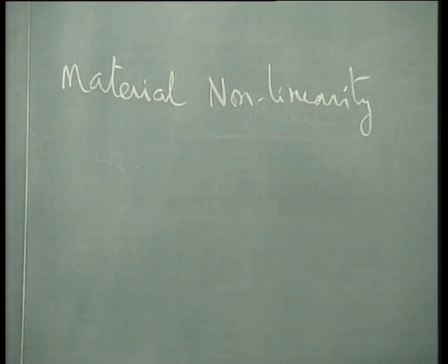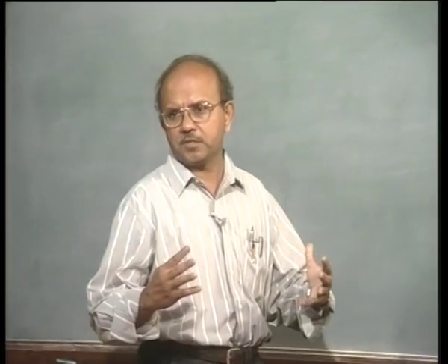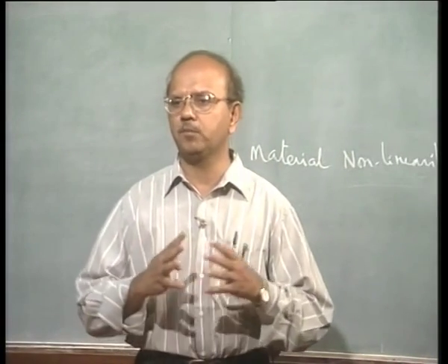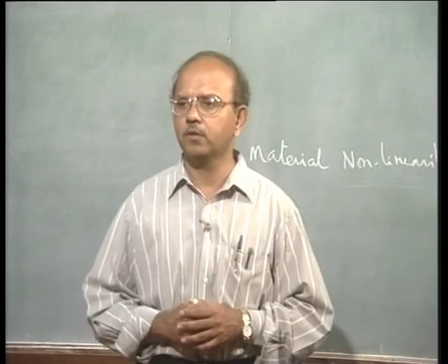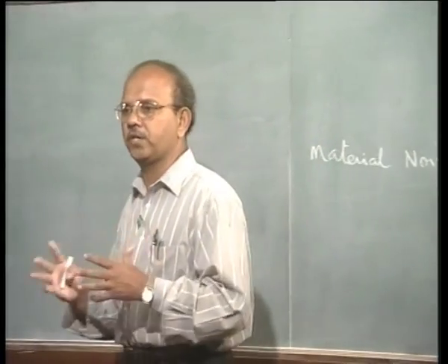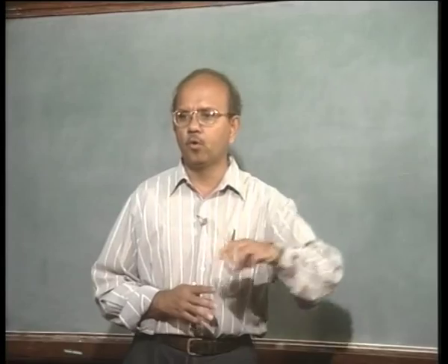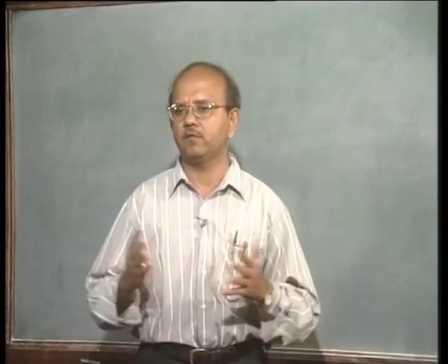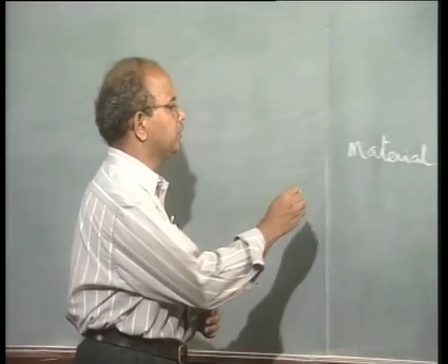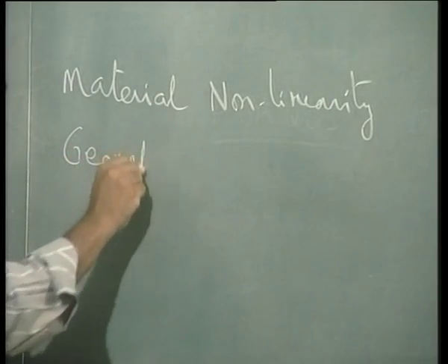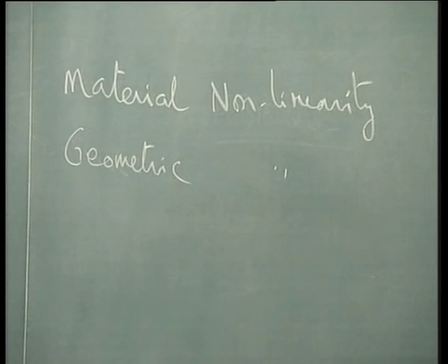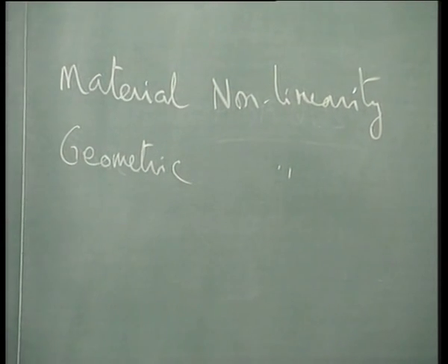Or the deformations, or the displacements, can be very large, though the strains may be small. The displacements can be very large, in which case the definition of stress is no more what we had defined here, the Cauchy stress and so on, and the way you define stress and strain has to be different. In other words, you can get into what is called geometric nonlinearity. When the displacements are very large, then you get into what is called geometric nonlinearity.